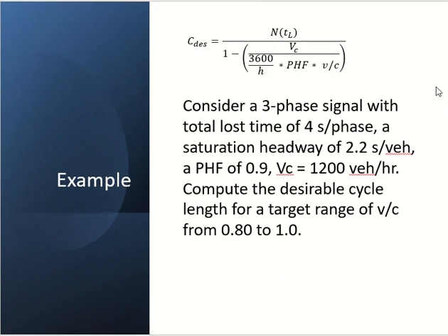The cycle length will depend on the number of phases we have. Yes. So it is not for one direction, red to red, right? No. Red to red is all directions finished. The signal turns from red again to red. That means all phases have finished.